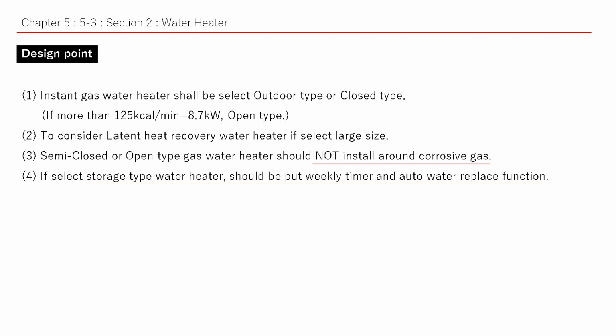These are the design points for water heaters. We would especially like to highlight item 3. A semi-closed or open-type gas water heater should not be installed around corrosive gas. Rapid rusting can cause accidents such as gas leaks. Item 4. If selecting a storage type water heater, a weekly timer and auto water replace function should be provided. If water stays for a long time, various bacteria will grow, so it is not suitable for drinking from a health point of view.